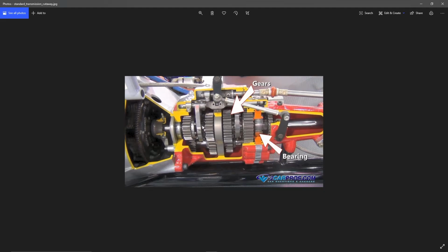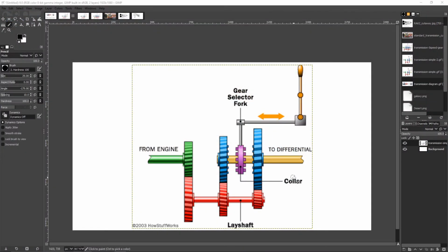And then you shift out of this gear, it disengages, these two are no longer splined together, and you spline these two together to achieve a different gear ratio. Power flow would go this way, down to the counter shaft, back up to the output shaft here, and then out. So not very complicated, not very big, nice and strong. However, these collars and these synchronizers that have to engage and disengage are going to wear out over time, especially if you're rough on your transmission.